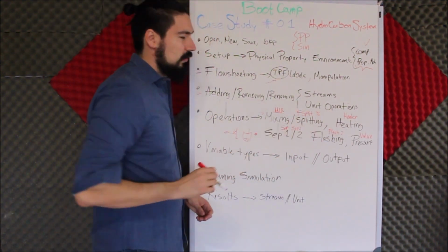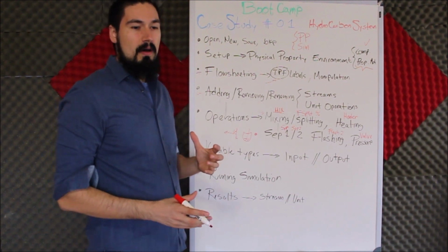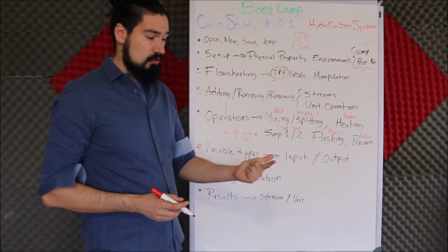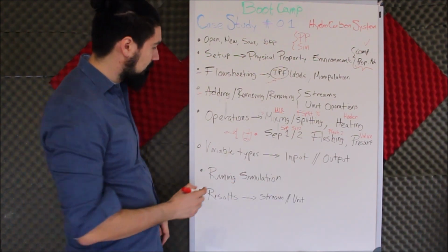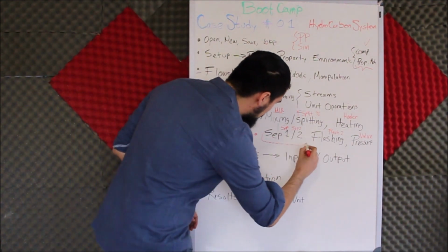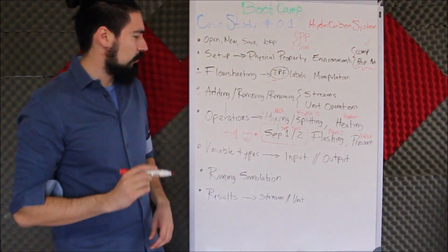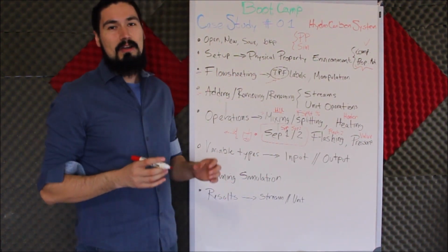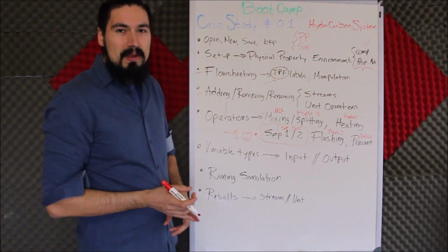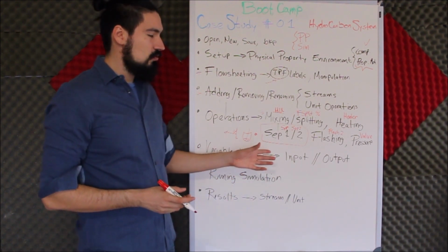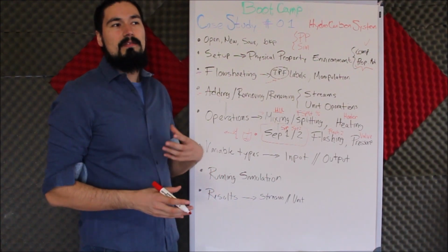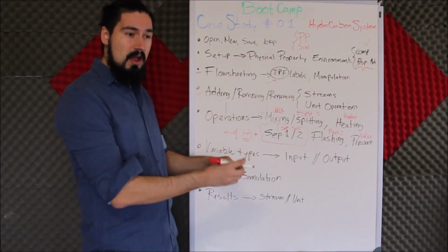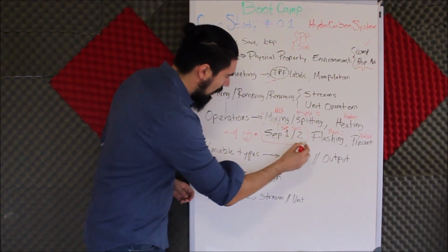Also, we're going to be working with heating, how to set up our heater in order to select vapor fraction, pressure, temperatures, heat duties. Then we will see this part right here, which is very important, the separator units. SEP1 and SEP2 are actually not thermodynamic based separators. These are used whenever you know that, for instance, if you're modeling a black box, you don't know what's happening there, but you still know that you have an outlet.